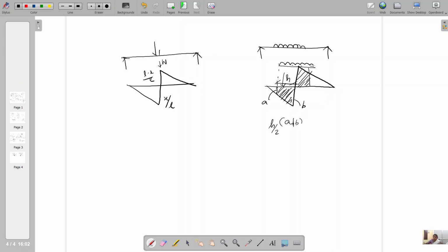So in this diagram, the shear force is the main factor which influences under the loading. So we keep this as H and this vertical ordinate as A plus B. If you consider this, you keep this as H, here it is A, this is B. So (A plus B) into H by 2 is the positive shear force. Here this area is the negative shear force when a UDL is located at a section X from A.